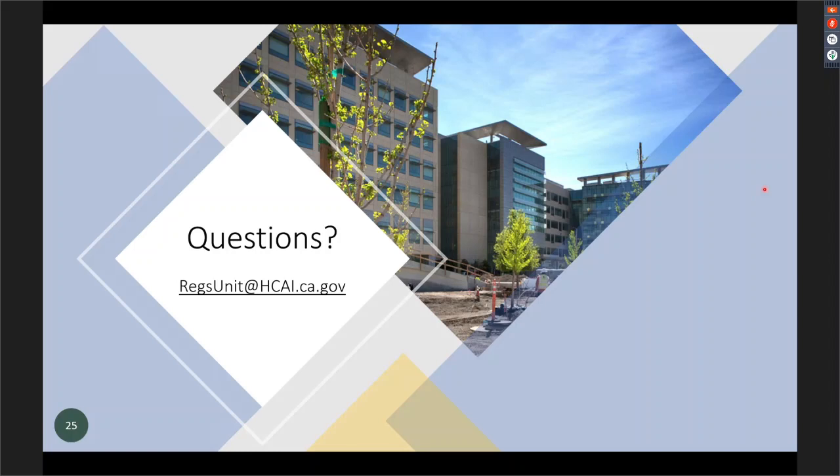Basically, the best examples would be where you're not changing anything on the drawings that would change the design. You're not moving walls, you're not moving outlets, you're not moving doors, you're not changing power, you're not changing HVAC, you're just answering a question for the contractor for clarification. Again, an RFI should be a request for information. The contractor's asking a question, you answer it.